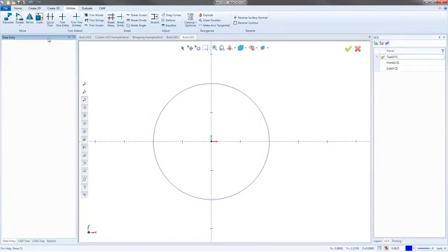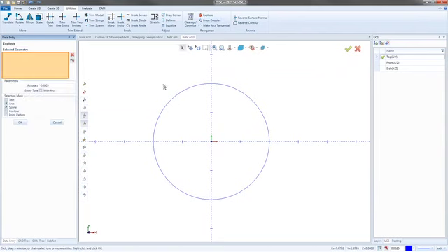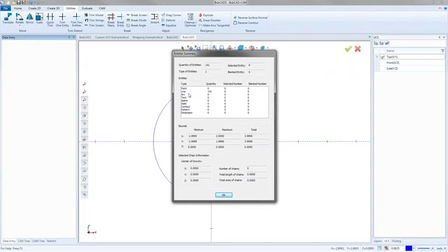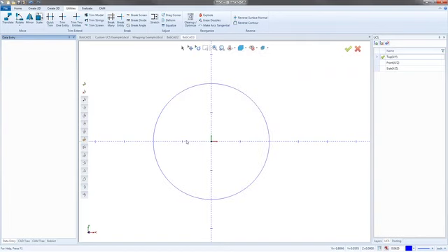All right, so the fit arcs option. So basically the explode function lets me break this arc into a whole bunch of line segments. I already did. Okay, good. And if we right click and go down to my entity summary, we'll see where we would have had just a single arc earlier, we have 141 line segments now, which equates to 141 separate lines of G code, which is real messy. So what I want to do is I want to rebuild this arc.